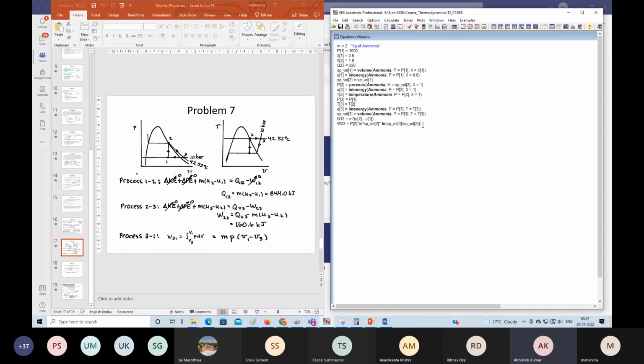So now let us go through this. We are considering this anyhow. So P2 V2 ln V3 by V2. That way we have calculated our work. We are not depending upon this particular thing. Okay, now what we need to do? W13. Yeah, W13 is what? That is P3 V1 minus V3. And since the V's are specific volumes, we need to multiply with mass also.